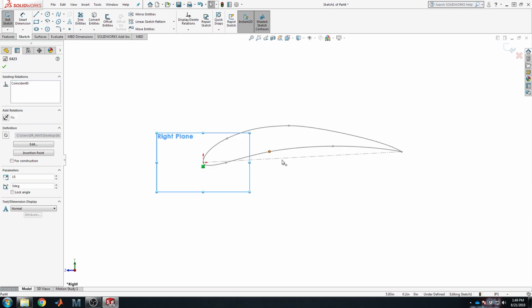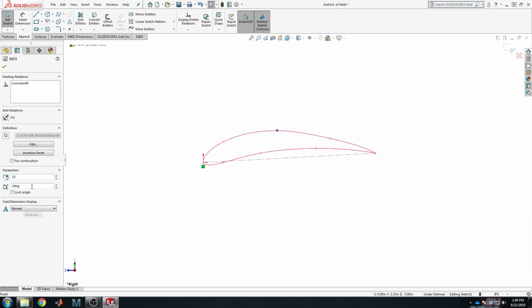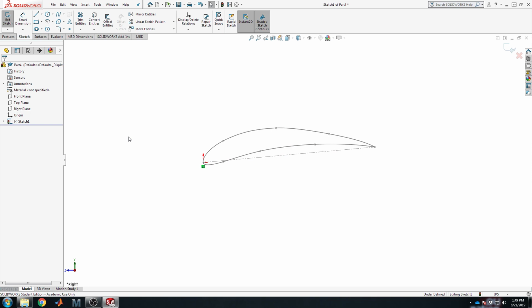I believe you can actually go back in here. If you click it once, you can change it. So if you're like, oh, whoops, 15 wasn't right, let's change it to 13. It's not stuck there forever in an unreasonable fashion. You just click once, change the angle. And what's neat is you can do this even after the airplane model is finished. If you've been robust in your definitions and the links in SolidWorks stay maintained, you can actively change washout.